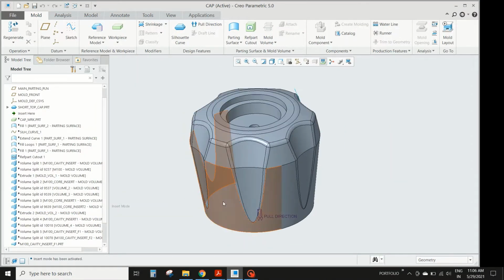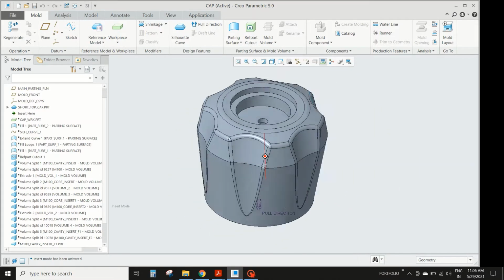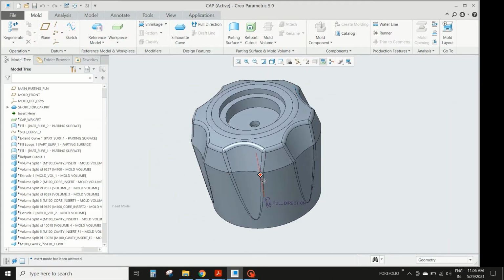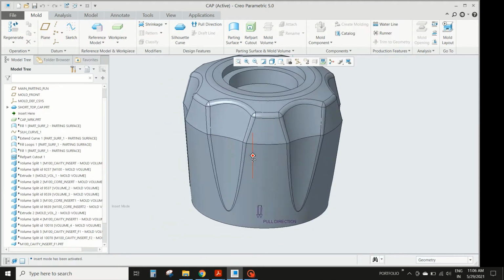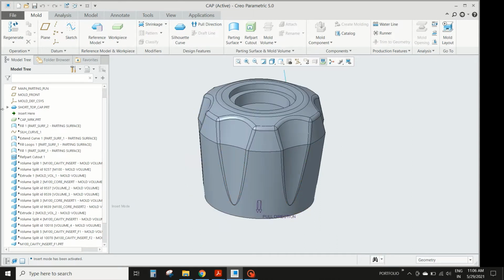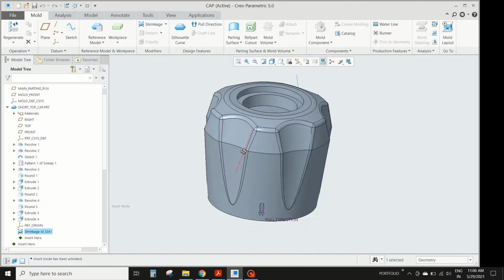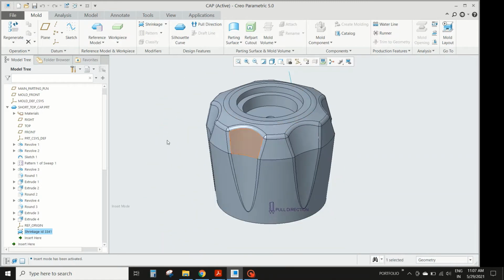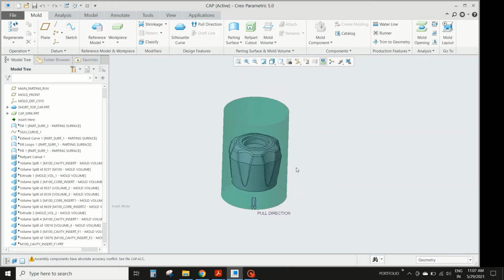So let's go into how to make a mold for this particular cap. If you are using Creo, you can open the model and locate the molding option, manufacturing and mold cavity. Once you bring the model in, you have to add the shrinkage value. In this case it is made out of polypropylene, so I have included a shrinkage value of 2%. Then you can make the core cavity insert.